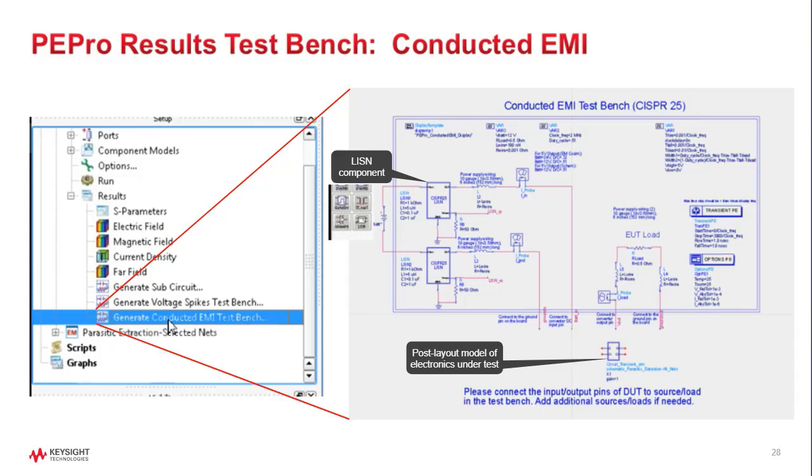And this particular example has, on the very bottom, in the middle, the model. So it has input voltage source and output load connections, and then connections to the test bench. You've got the LISN network itself, the load, some special configurations for running the time domain analysis and converting it to frequency domain. And in addition, we've also got the parasitics associated with the lead connections for the EMI chamber type of configuration in there as well. I'll show that to you in a live demo. It's a little hard for you to see that on the slide.